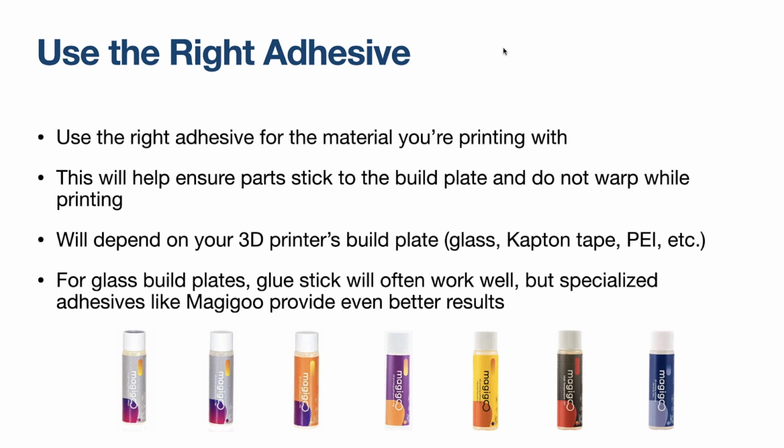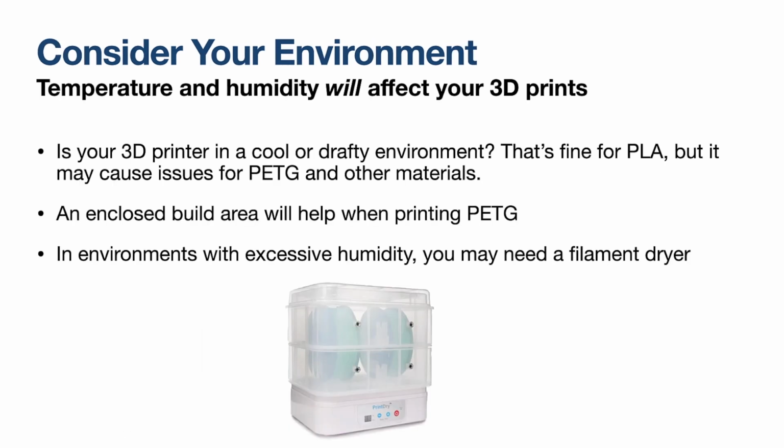But after the build plate cools, the adhesion sort of releases, and so your parts come off really easily. So I just love it. It's the only way I print these days. I always use some Magigoo adhesive. I just really love how it keeps the parts stuck on there while the bed's hot and then lets them go afterwards. Another thing that you want to think about is humidity.